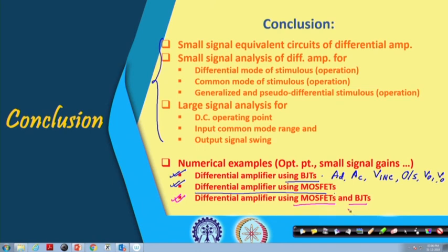Particularly what we have seen is that even though this differential amplifier's gain is not so high, differential gain was only 8 in our example, by replacing the tail resistor RT by an active device, one NPN transistor, that helps us to really suppress the unwanted common mode signal to quite an extent, and ensures that at the output we are getting almost complementary signals.